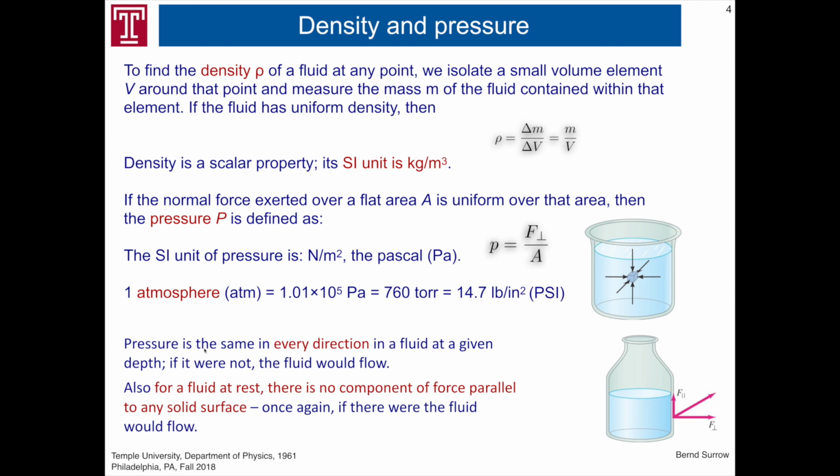Pressure is the same in every direction in a fluid at a given depth. If it were not, the fluid would flow. Also, for a fluid at rest, there is no component of force parallel to any solid surface. Once again, if there were, the fluid would in fact flow.